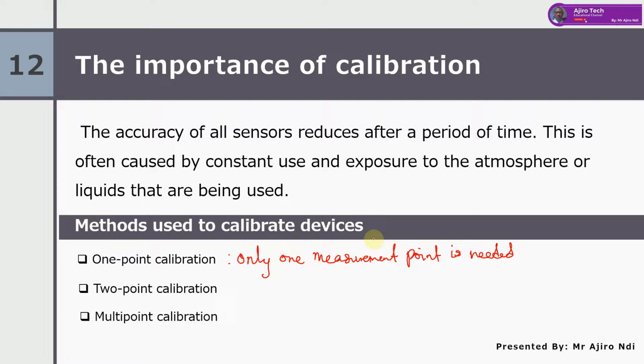This calibration compensates for both offset errors and slope errors, so the slope of the graph has to be considered. To arrive at this conclusion, we need to compare more than one reading with a pH sensor. It is recommended to place the sensor in solutions which are neutral, maybe pH 7, and either one which is acidic.